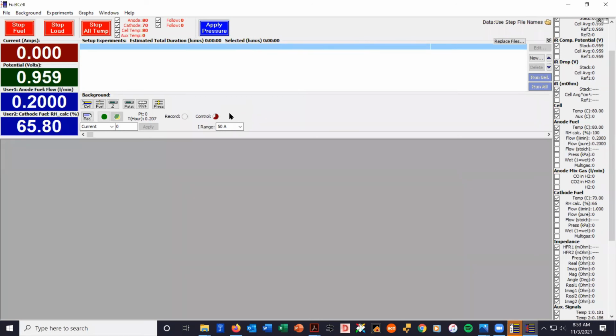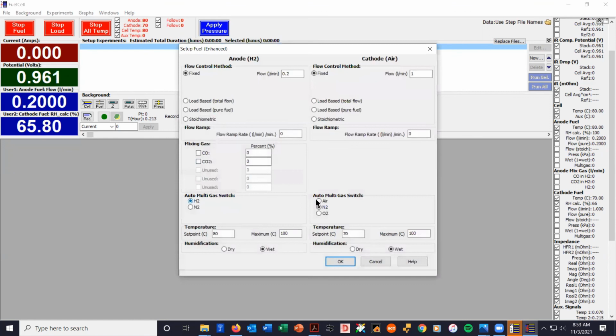An example would be measuring catalyst layer proton resistance. Something that people are really interested in studying these days is the resistance to ionic transport of protons within the catalyst layer. It turns out that you can determine that by doing impedance under hydrogen nitrogen conditions. But you need a potentiostat to do that, and it's an EIS based measurement.